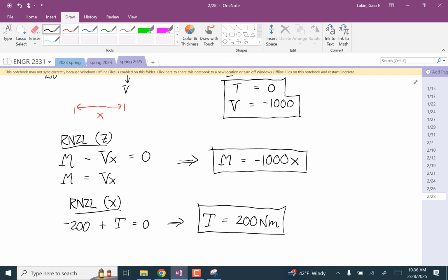So you have your wrench like this, cranking on it, this is fixed to a wall, and maybe you have another wrench that way. Then you'll have piecewise constant torques, one value up to here, one value after there. But what we won't see in any problems in this class is a continuously varying torque about x. But with something like this, you could.